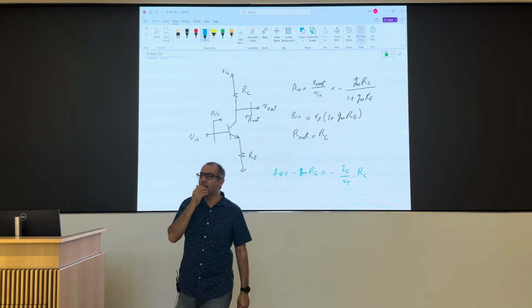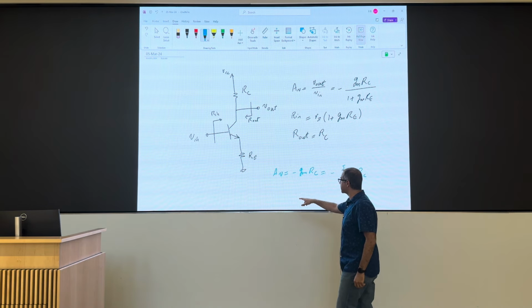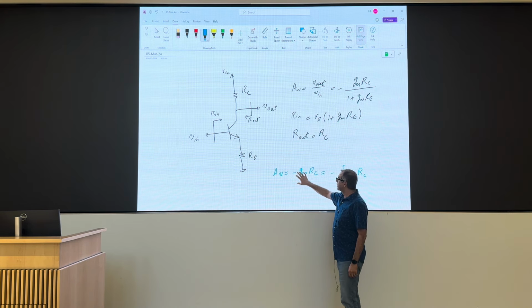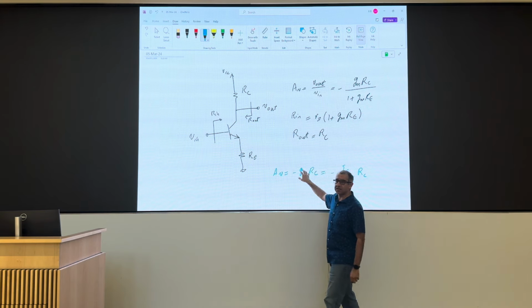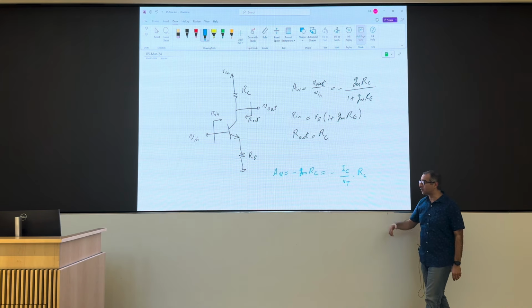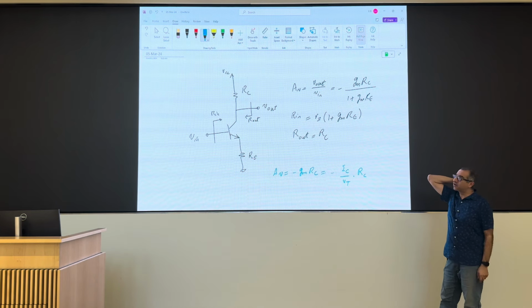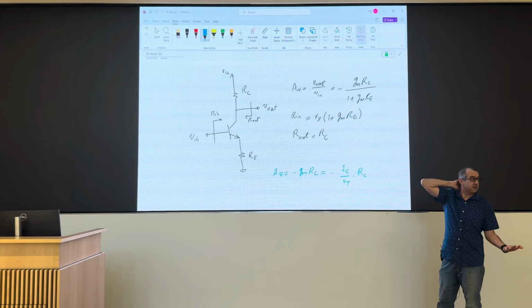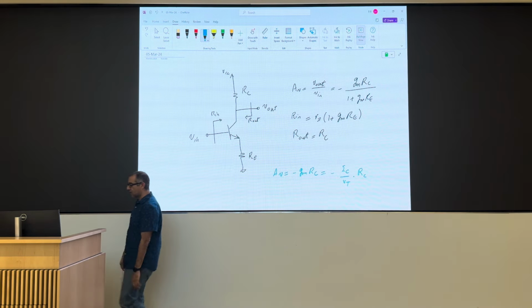There was a question here. So, sorry, just that equation is just for maximum. This is the intrinsic gain. This one, you mean? Yeah, that's not factoring in RE. Well, it's assuming RE is 0. That's the maximum gain you can get. So this is called the intrinsic gain, the maximum potential gain you can get. Okay? So this is the reason that a high gain amplifier may not have a lot of swing, because you have to put that collector voltage close to 0.